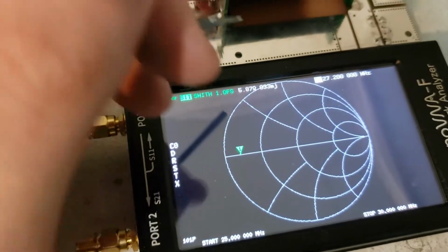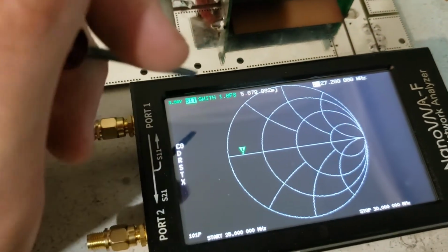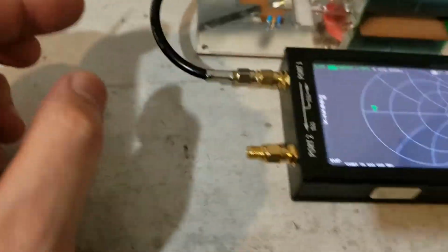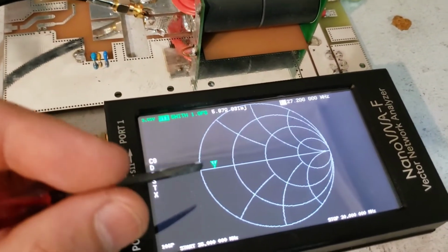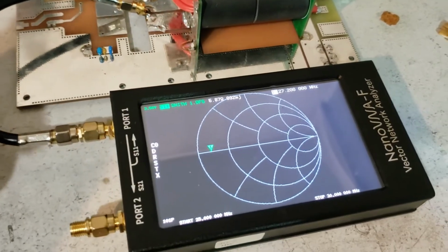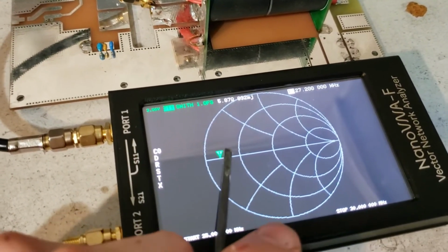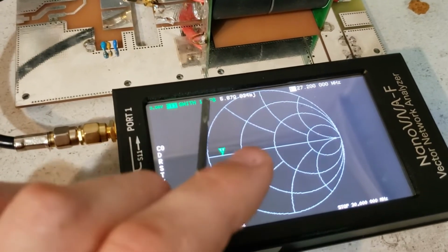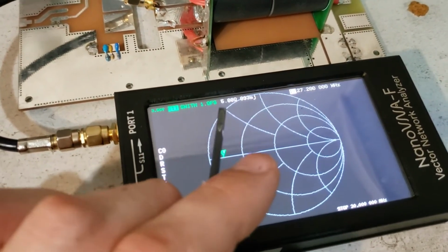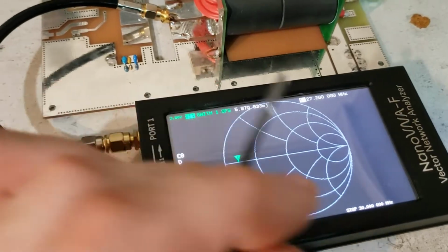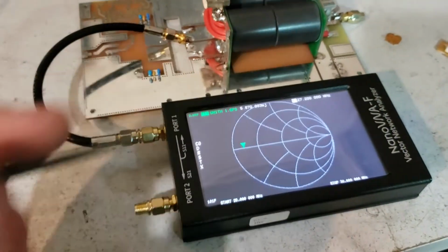The thing is most transistors probably aren't going to operate there. Like I said, this LDMOS chip here, it's pretty close to this impedance range. It's in that general vicinity. But your push-pull Toshiba transistors, they're going to be a little bit lower. They're going to be down in the 1 to 3 ohm range in my experience. But you know, don't quote me. Like I said, don't quote me.